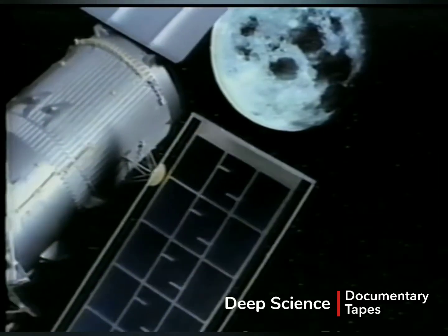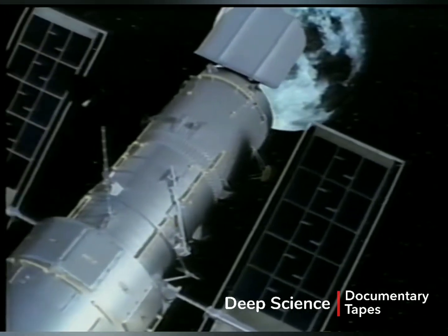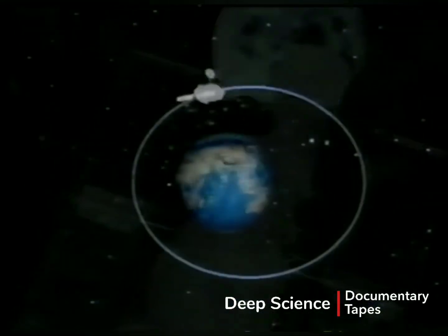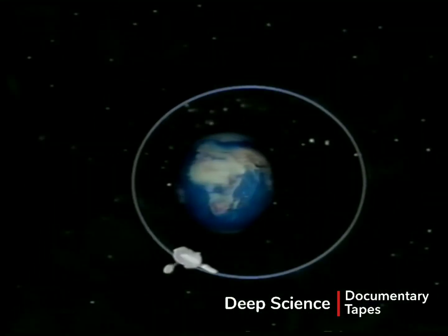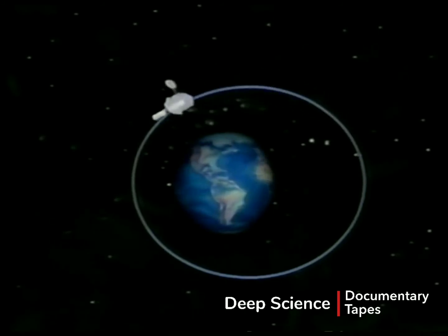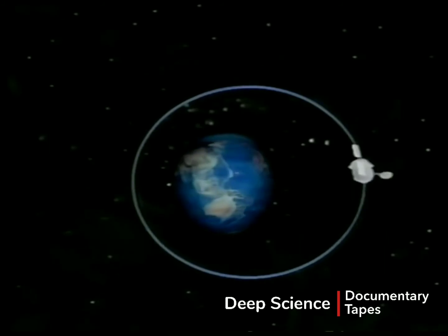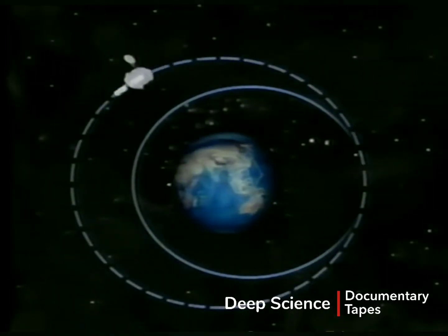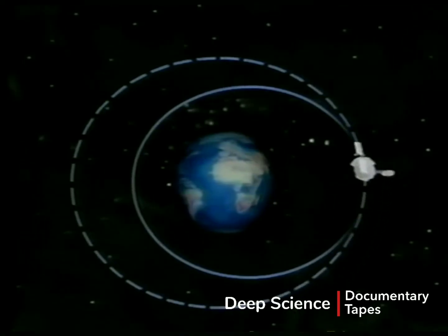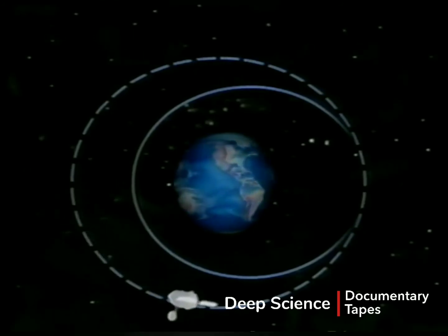On orbit, a spacecraft can thrust in any direction. Burns along the flight path, forward and backward, are the most common. A unique feature of any orbital burn is that if no other burns occur, the spacecraft will later always pass again through the point of burn. Forward burns increase the spacecraft's velocity and are known as posigrade burns. With posigrade burns, the flight path of the vehicle will be raised at all points except the burn point.